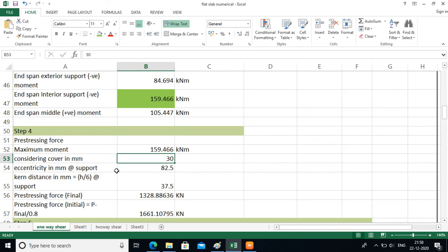When we change the position of the prestressing force, it can affect the result positively or negatively. So when we put the prestressing steel at the extreme position, that is, when we have the maximum eccentricity, we get good results for the prestressing force even without increasing the number of tendons. That's why we have taken the maximum eccentricity here.